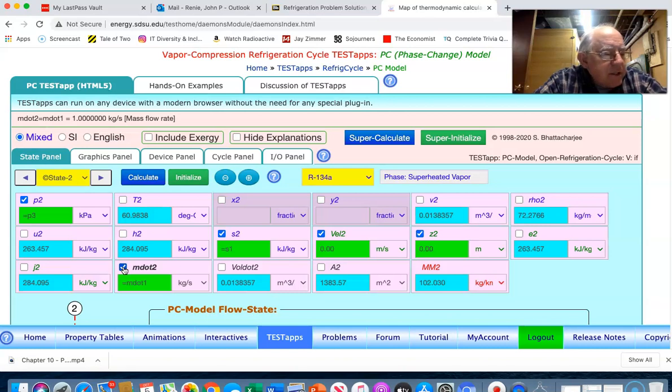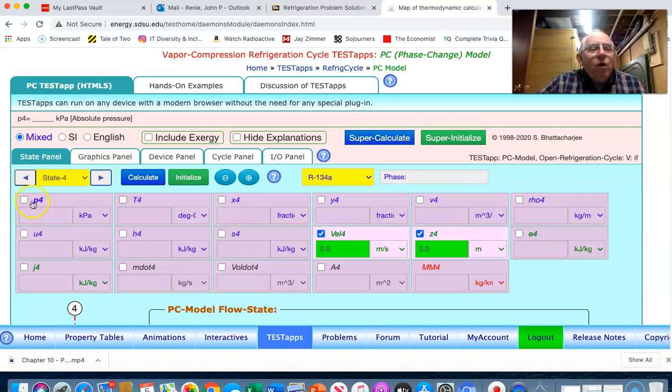That gives us the output of the compressor. We see that the compressor generates a fluid that's at about 61 Celsius, and it's going to desuperheat down to 55, and then it's going to go through the condensation process where it goes to liquid at 55. The final state then is state 4, and state 4 is at the pressure 1 that we've already established.